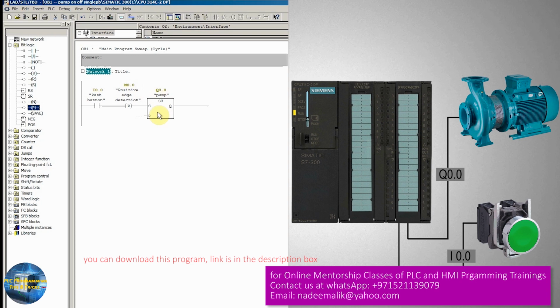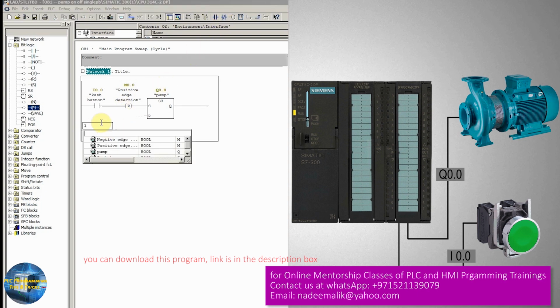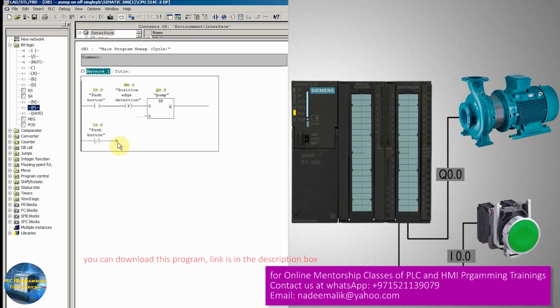Once the output Q0.0 is high, the next step is to turn off this Q0.0 output whenever we press the I0.0 push button again. To do this, we will insert a branch here, and we will use the normal close contact of the input I0.0. Once the output Q0.0 is on, we can use its normal open contact here.